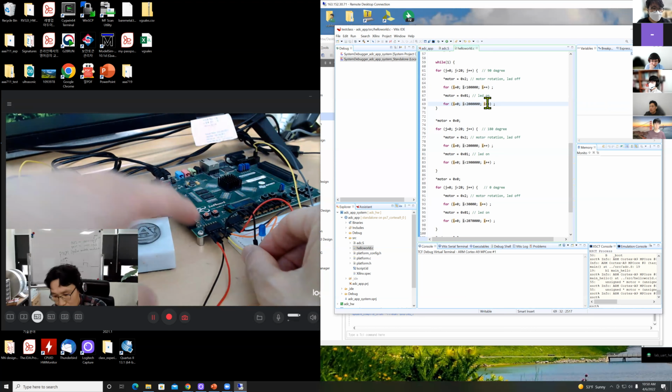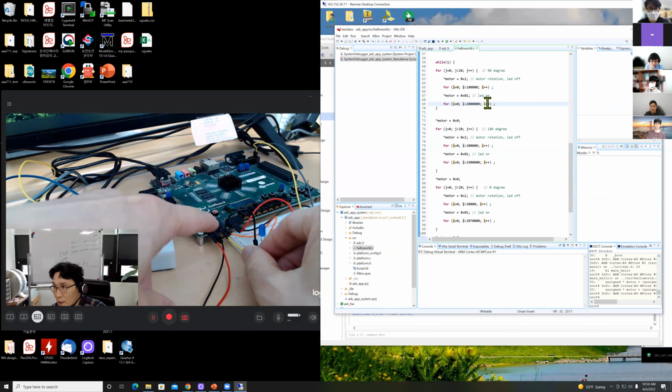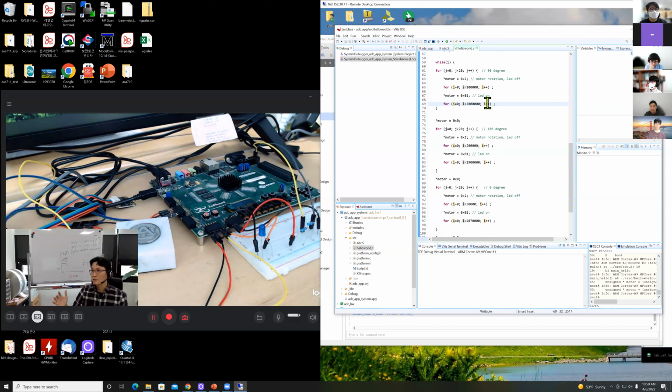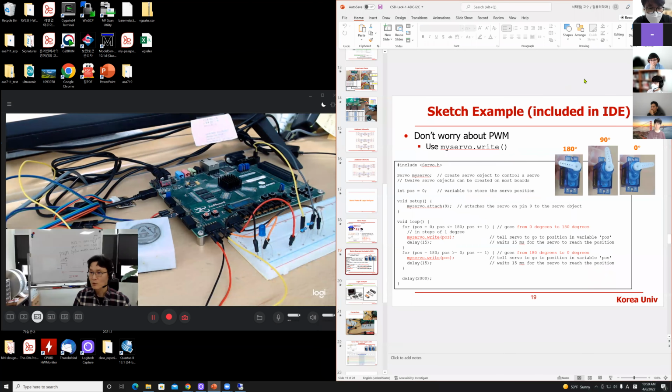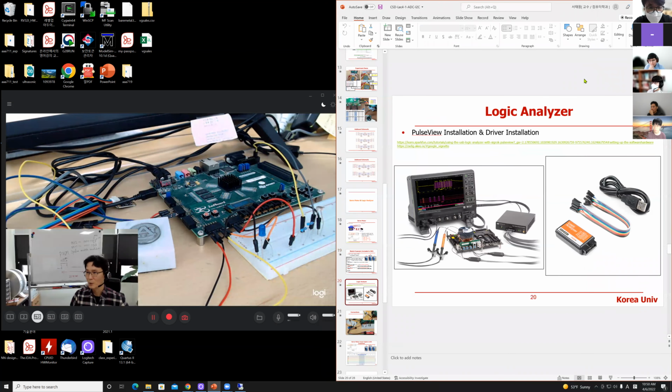You want to tap into that wire, then see the waveform, right? As you run this software, you want to check out that wire status. This yellow is wire status. Is it generating the right pulse or not, right? So that is why I gave you this logic analyzer, very cheesy logic analyzer, this one.